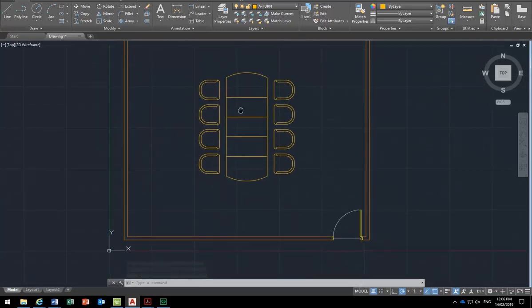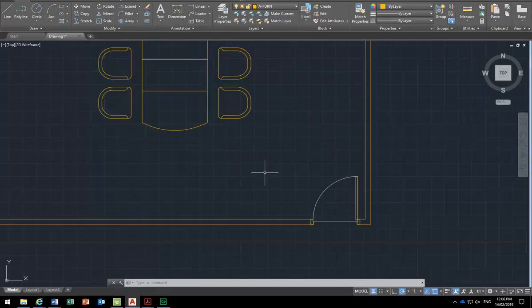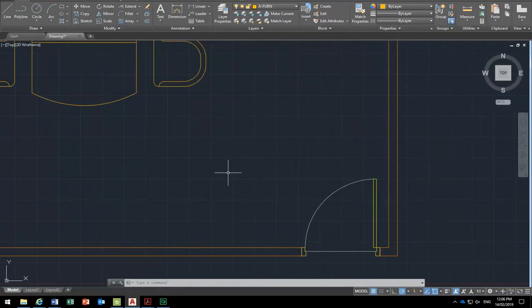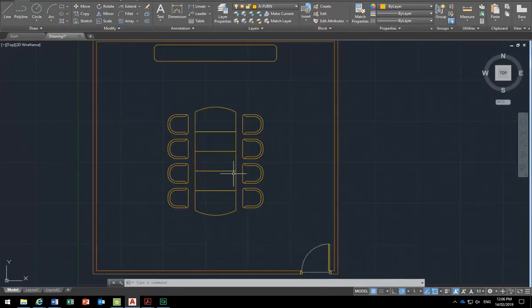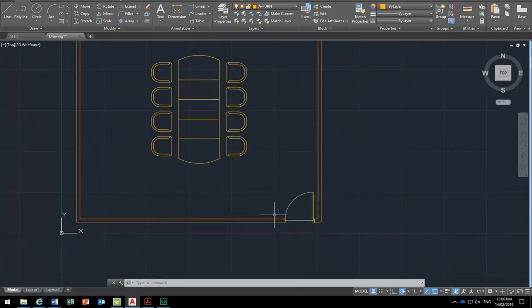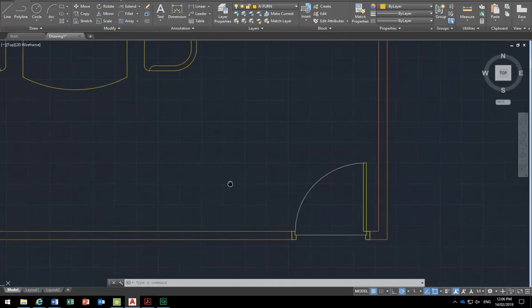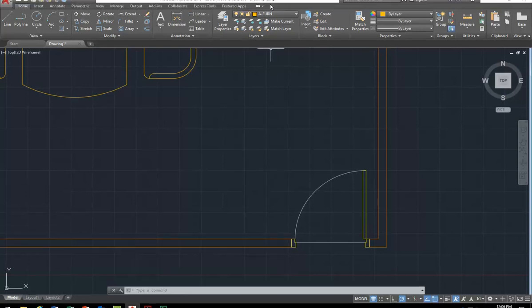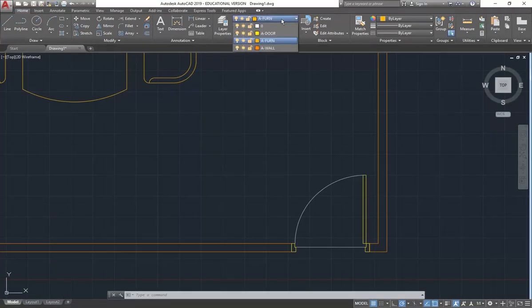So the wall I'll do next. So this now, when you get to do things like this, all the little fiddly steps I just showed you, you'll often be able to work out as you go, but what you really want to make sure you're comfortable with is those initial commands, drawing lines and then offsetting and filleting and trimming them to make things like walls. That's going to give you most of your, especially floor plan drawings, but sections and elevations as well.